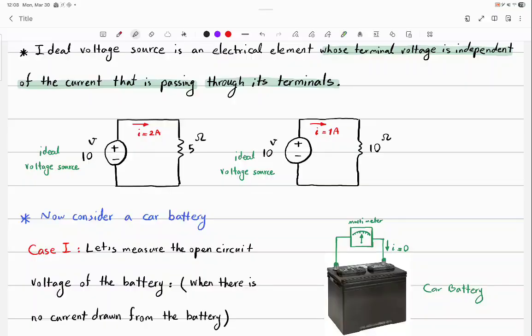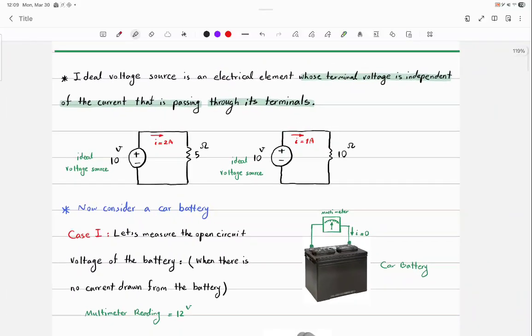For example, the voltage source that you have on those workstations is a practical voltage source. Why do we need to consider some internal resistance for it? Because inside that box, there are a lot of parts and wires and everything, and they all have resistances, right? So it's not zero. Ideally, it would be zero, but it's not. That's why we have this case.